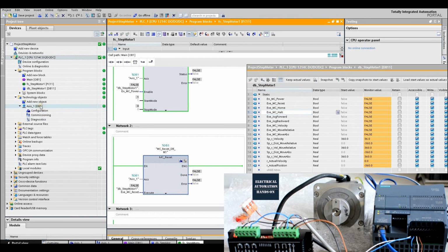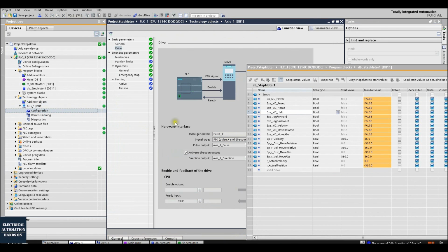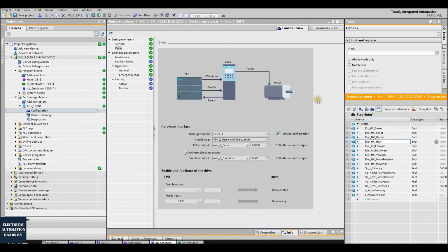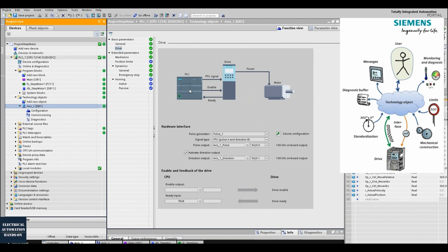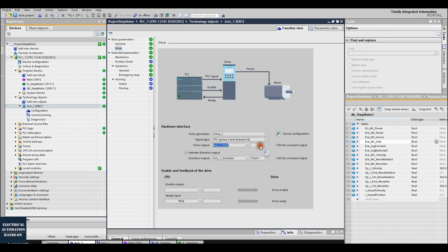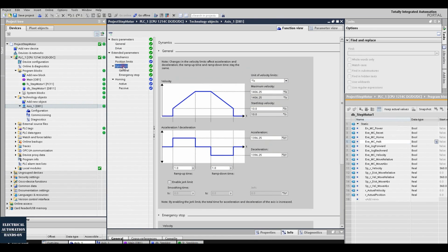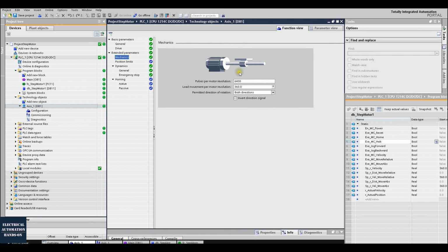So typically, if we review, we create this axis and then we use the configuration. Basically this axis on the PLC side will run as a driver. This driver joins the program and the hardware together. So at the right side, this is the hardware. We assign the hardware channel and also assign some mechanical data: maximum speed, the start-stop velocity, and this scaling, this load movement configuration.